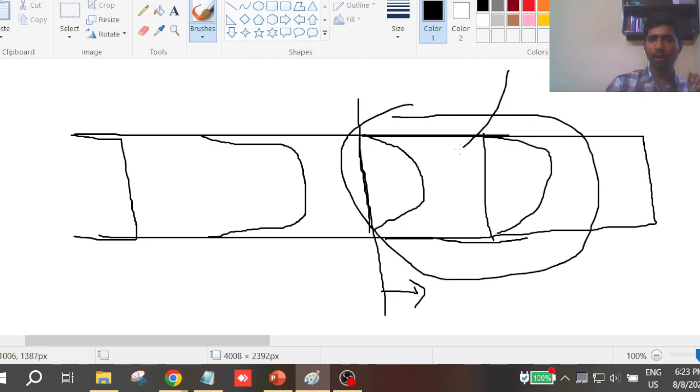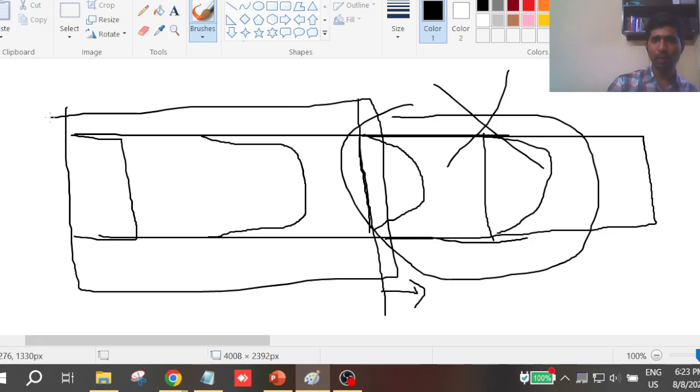So we are not interested in seeing this picture at all. Why do you want to see this picture? It's not changing. Only things in this particular domain change, so it is better to select only this domain length. That is the optimum length. You can select more also. Ideally we select a somewhat higher length, but you cannot go to a very large extent, because you need to discretize this.